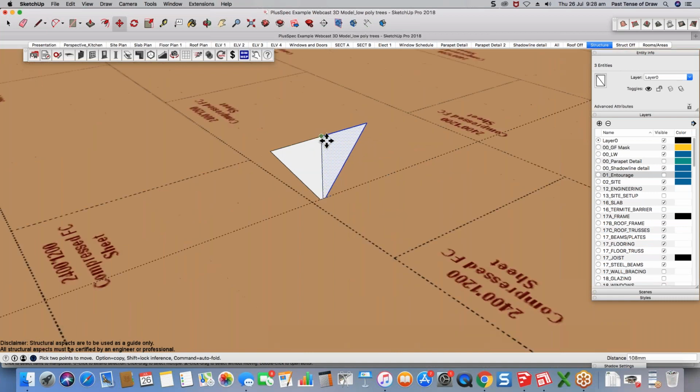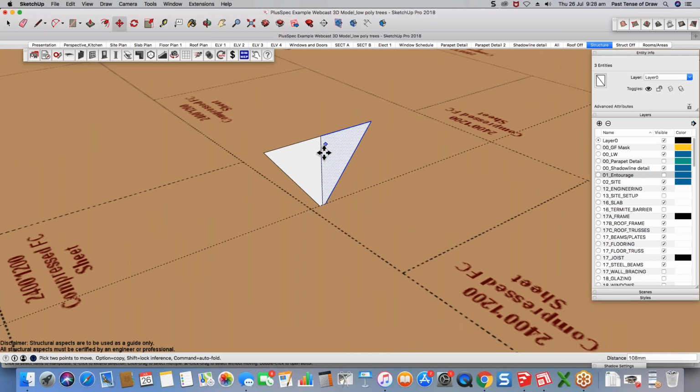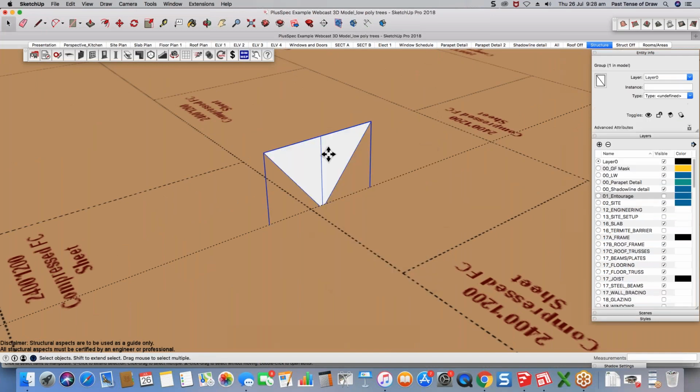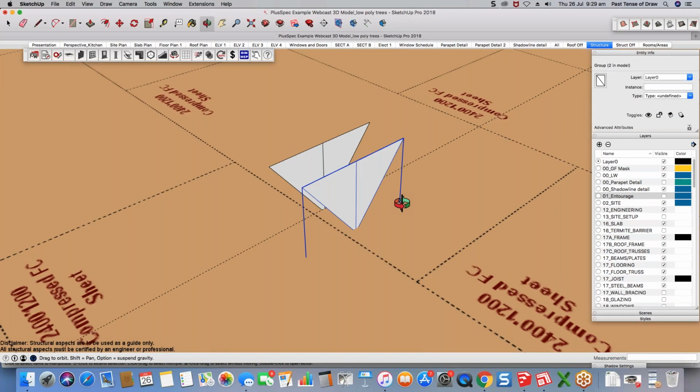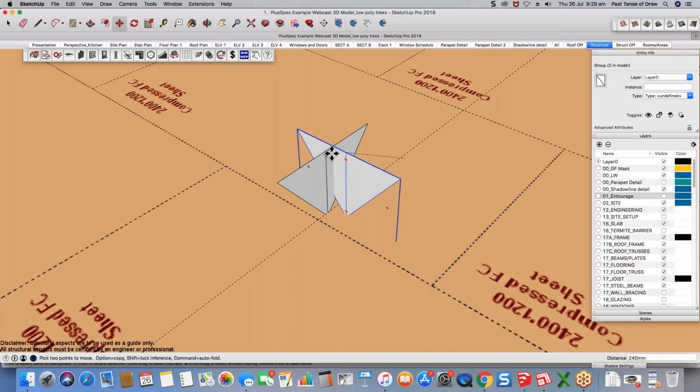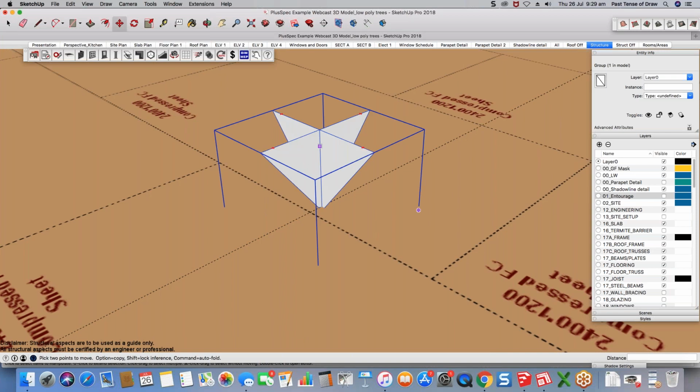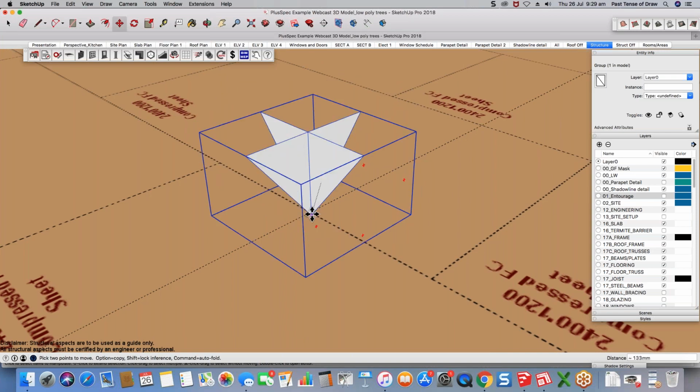Okay, so I've got the first one, make group, could even copy it, and I'm going to rotate it by 90 just so it's on all sides. Just to give you an example of what's going on here. I'm going to turn that into a group, and now I can move it up. I've got my point, and I can locate it directly on something in my project.